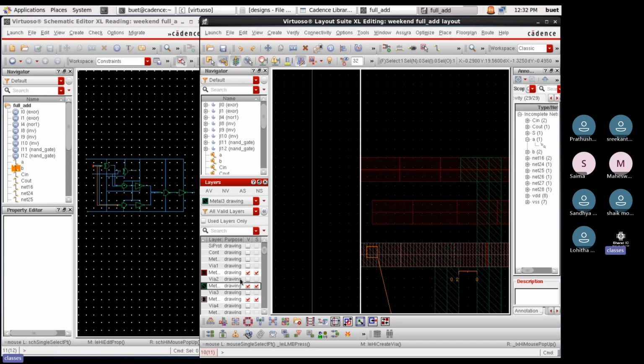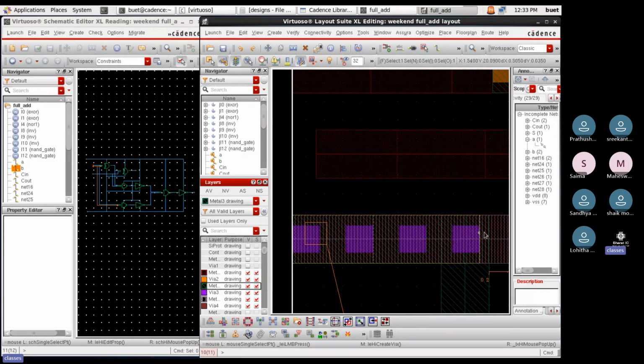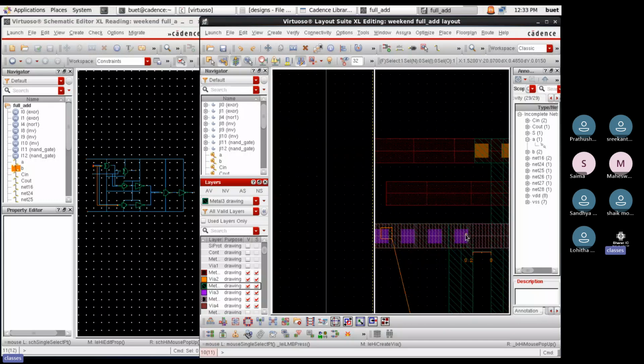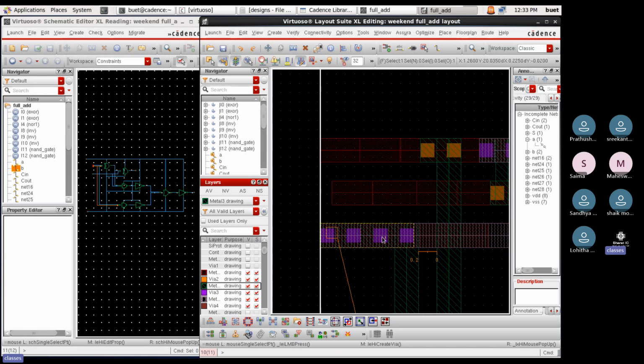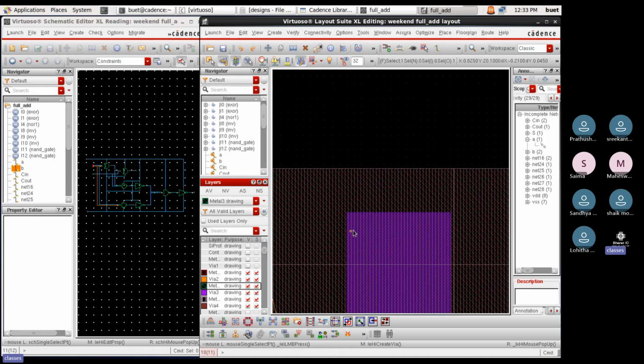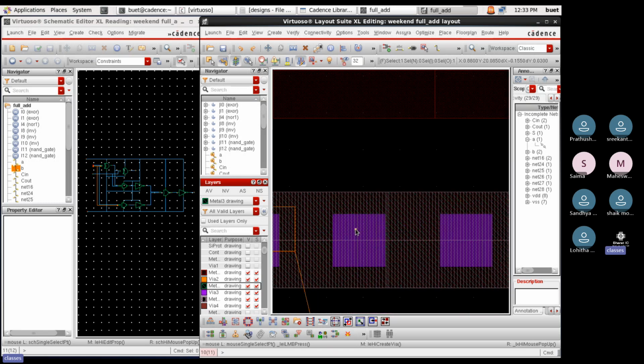Okay, now if you see VR2, VR3, okay, and VR4. Now this should be fine. It is connecting them individually, it is connecting them properly, and even this is connecting the M3 metal also. What I have done, you got it? I have just taken a M3 to M4 via, and I have put it on top of this one by aligning these contacts with the previous one. That only I have done simply, which will help.